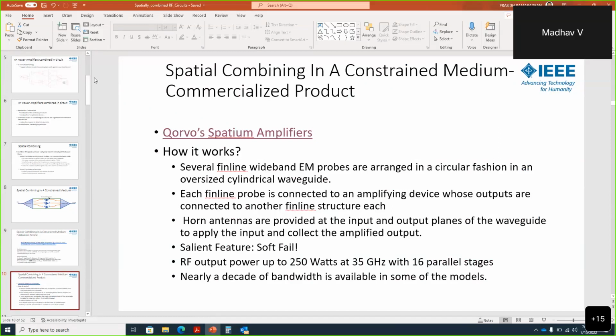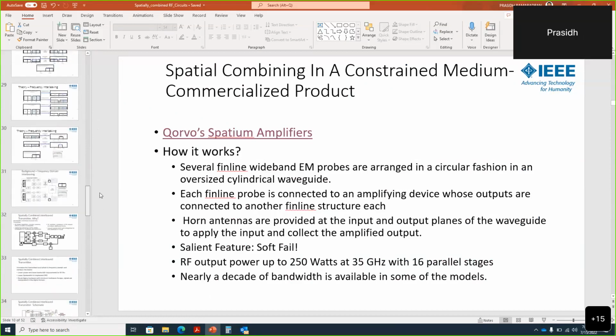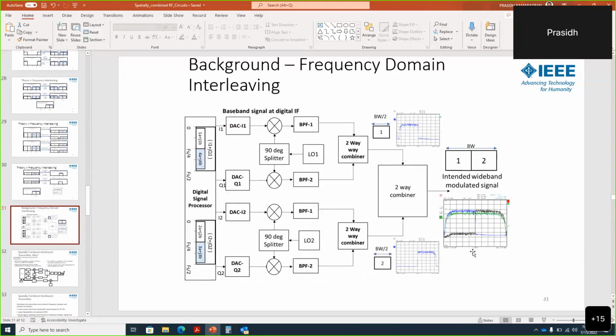Well, it is applicable to contiguous. That's actually the reason it was first experimented with on a contiguous spectrum, with a single carrier modulation scheme here. So you can see that essentially the ACLR of this falls here, and the ACLR of this falls here. Okay, but that is low enough to not cause EVM degradation and things like that, is it?